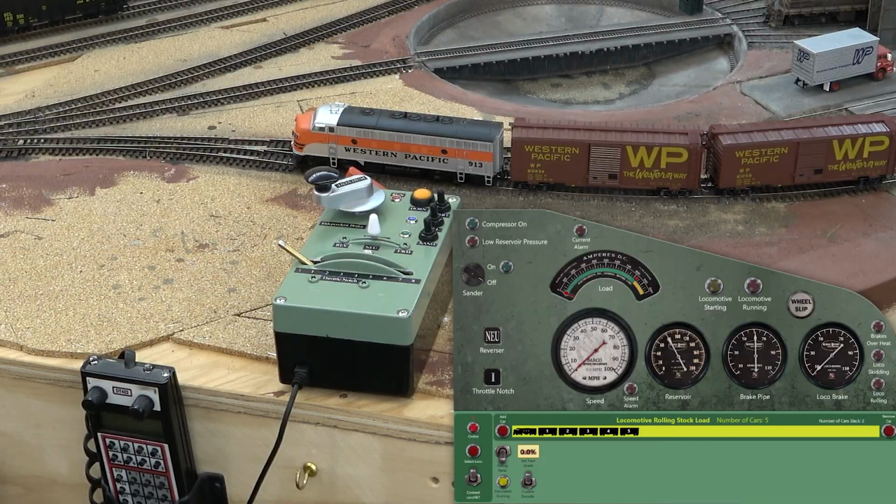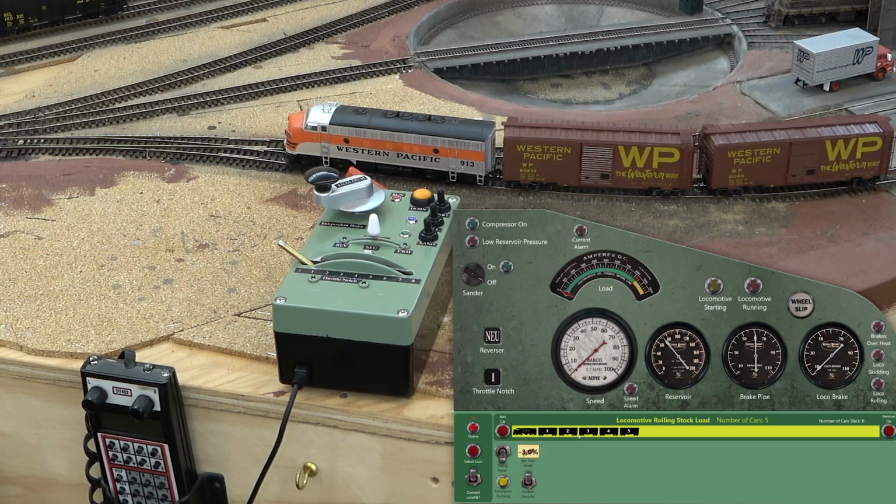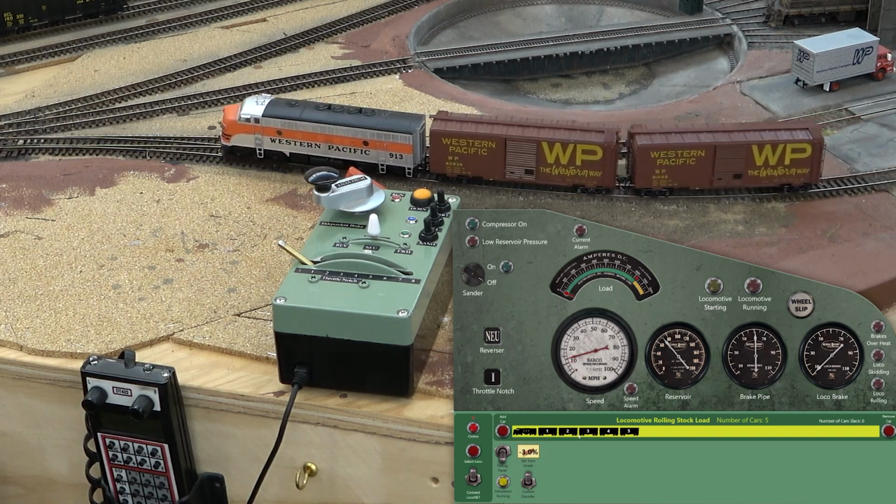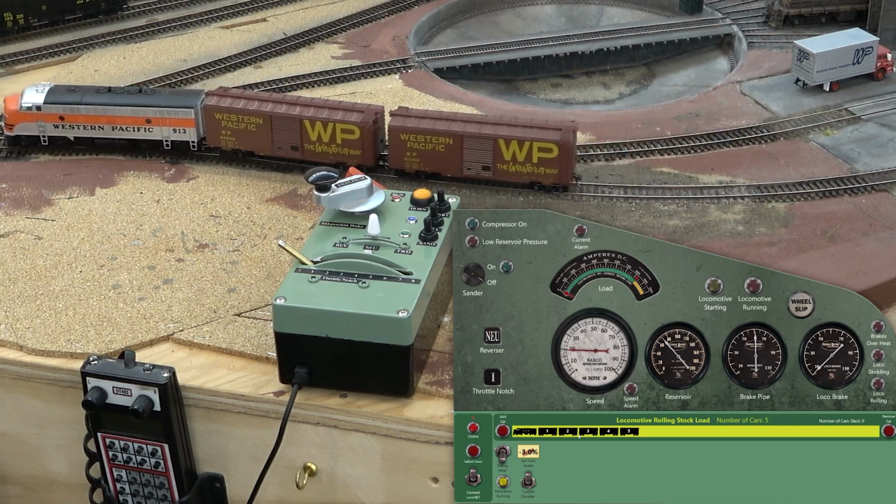So now I'm going to do kind of an extreme thing. With the locomotive off, there's no brake pressure on the locomotive. The brake pipe is filled, but essentially this train has no brakes on it. It's just sitting there. And even though we don't have the locomotive running, the simulation is still running. And so I'm going to go and change the grade. See what's happening? We've got a runaway.